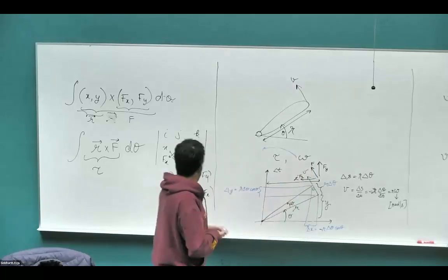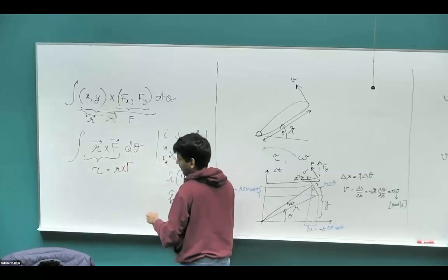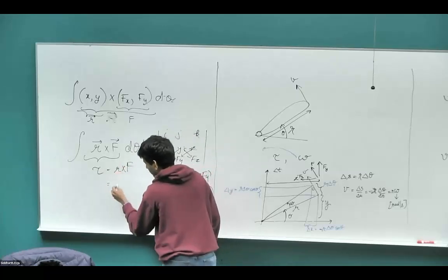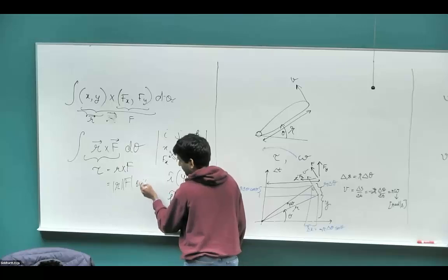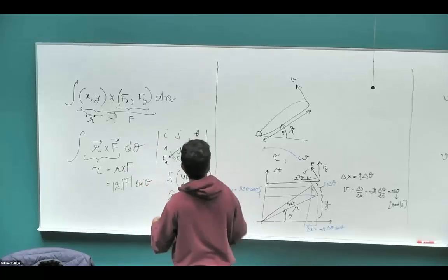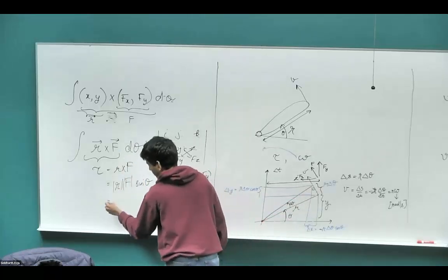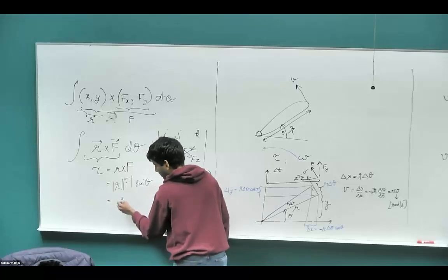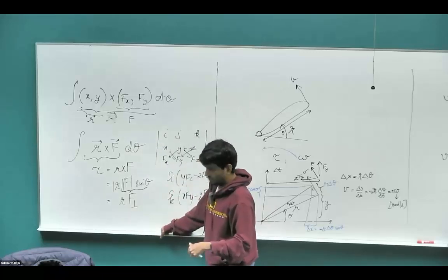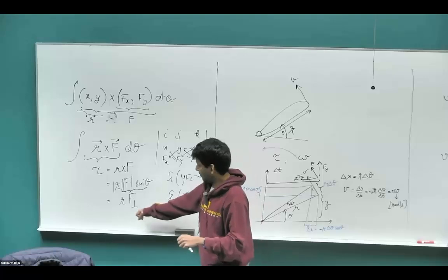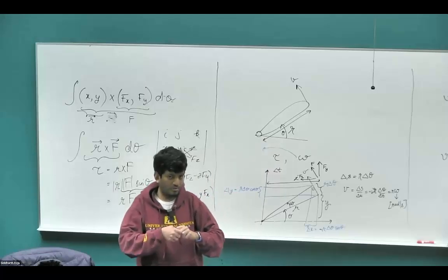That is always going to be perpendicular. So in this class, we are always going to consider only the component of force that is perpendicular to our radius. So this in turn is the magnitude of the radius times the magnitude of the force times sine of theta. Going from here to the expression I've written on the right is just basic algebra. You can substitute those values and you'll see that all the expressions I'm writing here are exactly one and the same. And this is the same as saying it's radius times the force that is purely in the perpendicular direction, right? So going forward, if I give the force purely in the perpendicular direction, you don't have to worry about clockwise, it's just radius times the force. Anybody got any questions so far?